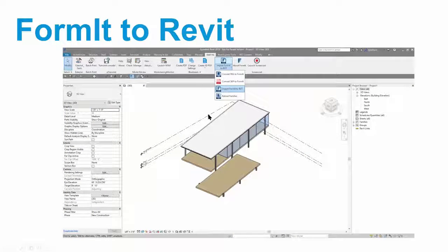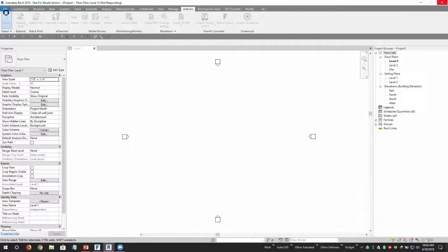So if I select that and up on the ribbon of Revit, when I say edit family, I can go into that and then go to switch category to be able to switch that to a column category so that Revit knows that it's a column. So if I go to schedule it, it's going to show up as a column in the schedule. So let's see how Revit's doing here.